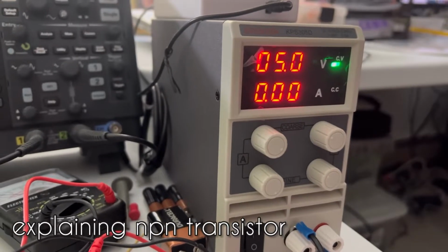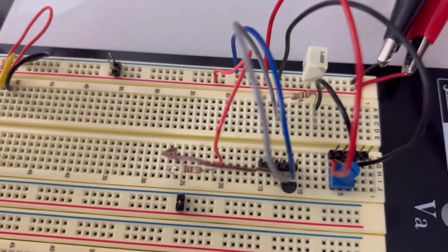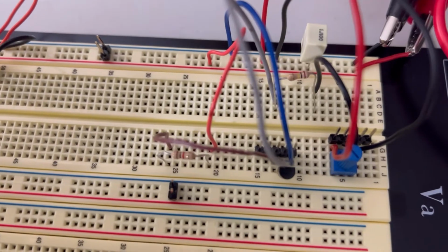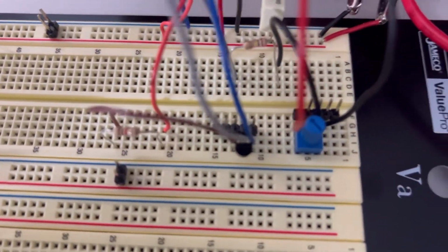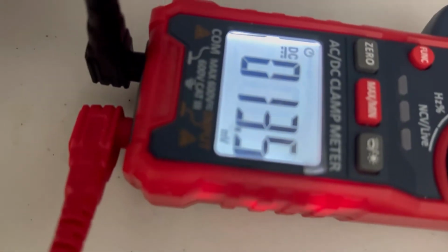So starting with a power supply of 5 volts, this is the circuit that we have built, circuit 1 of the NPN transistor. We're going to measure the voltage between VADJ and ground, which is 4.98. Earlier we had measured about 4.96.